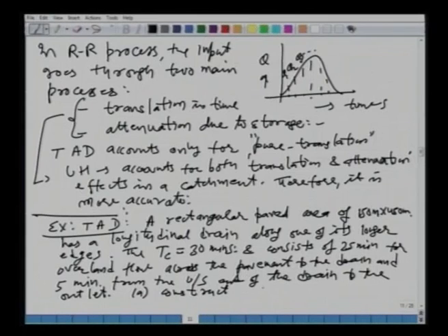Okay, what you have to do is A, construct the isochrones at 5-minute interval. So we are looking at this example. A part we have to construct the isochrones at 5-minute interval, and B, in the second part we have to develop what is called your time area diagram.